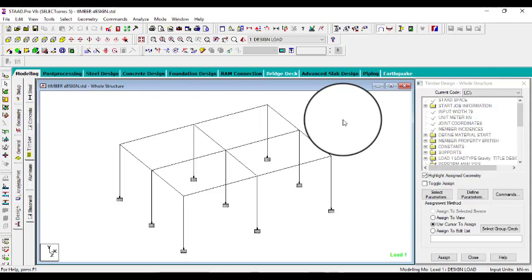Then in the next class we will discuss a timber roof, a roof truss, where we have the load due to the purlin, we have the load from the roofing sheets, we have the load from the rainfall. So basically what we have to do there is just the difference will be in the loading and then the compression and tension members. Okay, the design will still be done the same way.